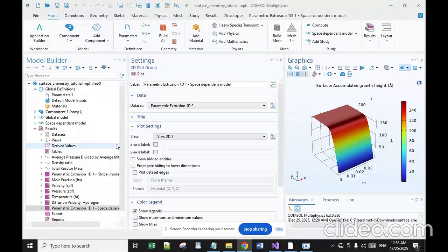Glasses containing both boron and phosphorus undergo viscous flow at lower temperatures. Around 850 degrees centigrade is achievable with glasses containing around 5 weight percent of both constituents. But stability in air can be difficult to achieve.